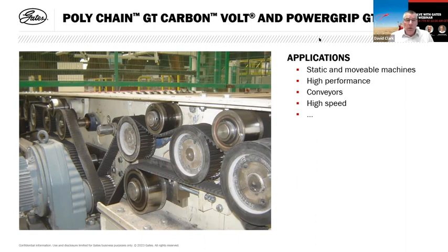In many cases, if you're using standard pulleys, these are quite often relatively low quality steel or cast iron. They have a maximum speed of 33 meters per second. That's not a restriction on the belts, and our belts can run at speeds higher than that. But in order to do so, you tend to need non-standard pulleys with dynamic balancing. So belts can run at speeds greater than that. It's just that you need to make sure that the hardware is also suitable.